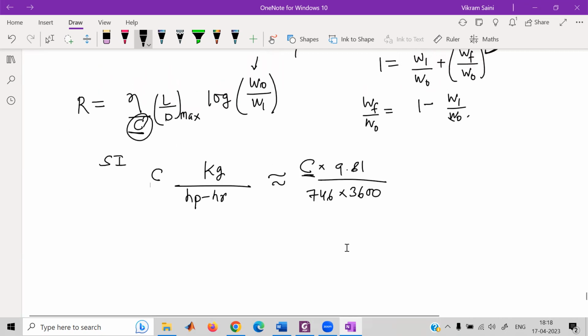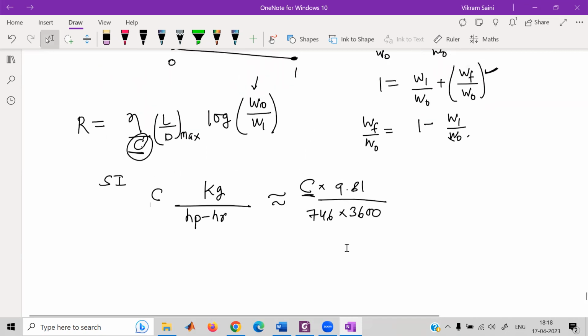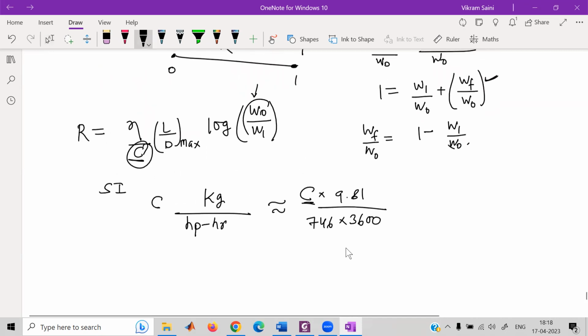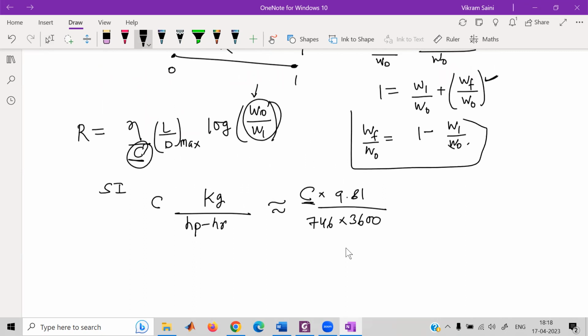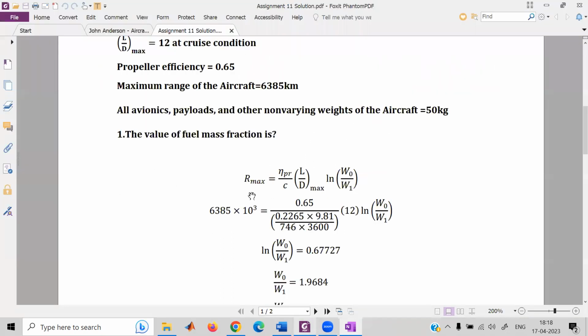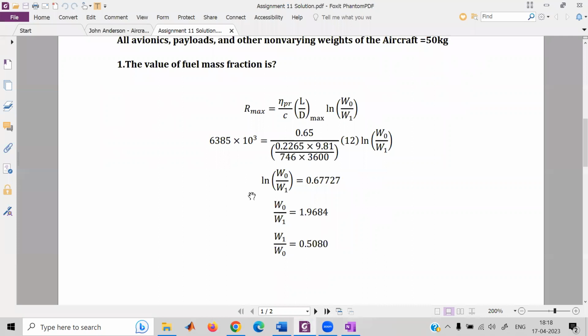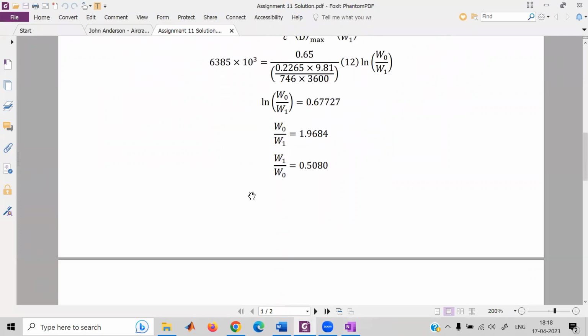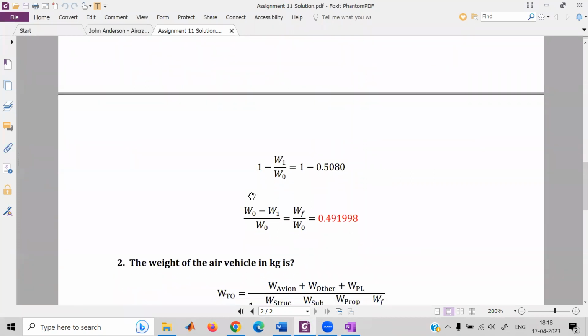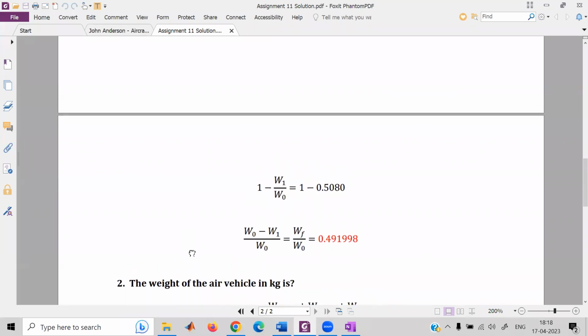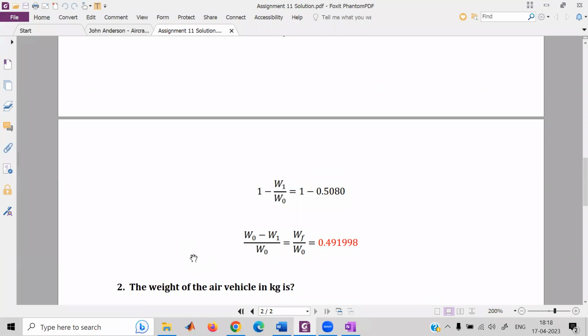And the efficiency is also given, probably 60%. You have this fraction here, you reciprocal it, and then you substitute and get the fuel fraction from here. I hope everybody now understands what we're supposed to do here. So we'll go to question number 2. The weight of the air vehicle in kilogram is...